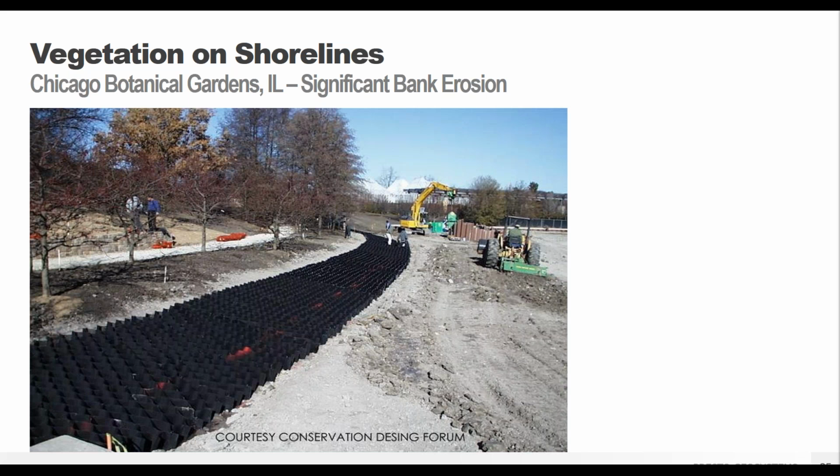And so, like I said, they put in the sheet piles. You can see them there to de-water. Because this was both a really narrow, very small slope, and also a pretty shallow slope, they were able to use stake anchorage. That is a little bit faster sometimes, especially when it's a really small area like this. The stakes might go in a little quicker than a tendon system. So something to consider. And then the GeoWeb was actually filled in with native soil from the pond. And then the same plants in this botanical garden were placed in there to try and grow. So this would end up being a seamless look overall.